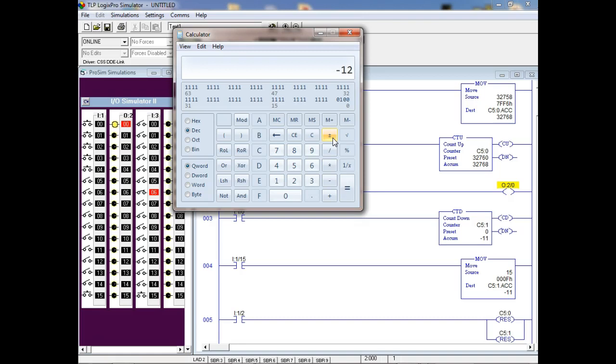So what that does is when we use 2's complement, we take the maximum range that we've got, and then we divide it by 2, right? And then we drop 1 off for the positive. Because 0 occupies one of the positive slots. And that's why these signed numbers are limited to a minus 32,768 and a positive 32,767, right? Because 0 occupies one of the positive slots. Does that make sense? 2's complement is neat.